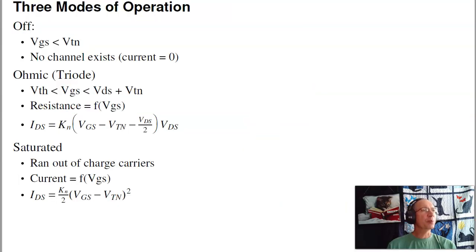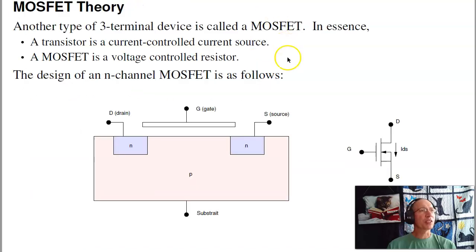In industry they use MOSFETs, but in lab we don't. The reason is this gate right here is a little capacitor. There's a small insulator between the two. If I apply too much voltage from gate to substrate, I discharge across that insulator and I burn out the MOSFET. MOSFETs are susceptible to static electricity, so they don't survive our labs very well at NDSU. In industry, where you have more static protection, MOSFETs are really what you use. We use BJTs just because they survive our labs. Really, in industry, you want to use MOSFETs. They're smaller, cheaper, more powerful, quicker, but static sensitive.